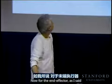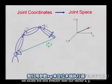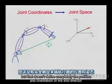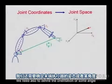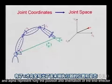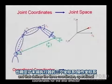Now, for the end effector, as I said, we locate the end effector with a vector x, y, but that doesn't completely define the position and orientation of the end effector. We need also to define the orientation, some angle. So we need alpha, and then x, y, and alpha fully represent the position and orientation of the end effector, and that defines the three operational coordinates for the end effector.